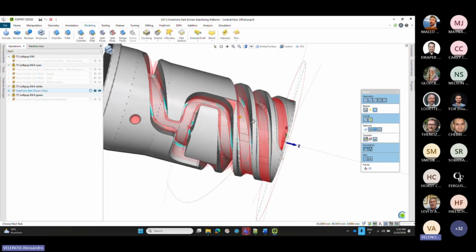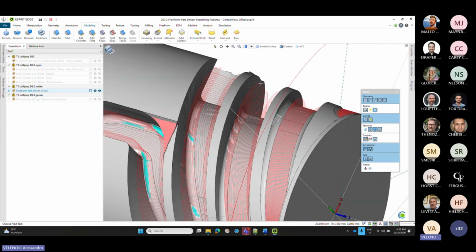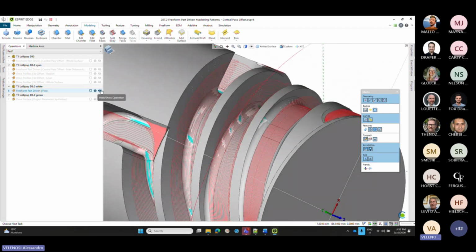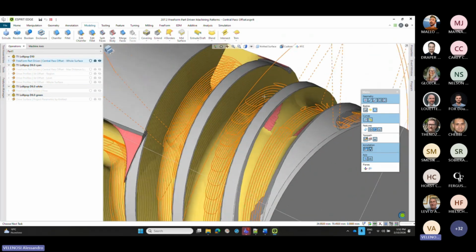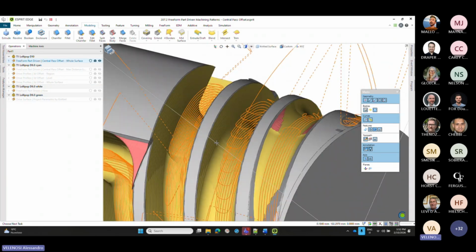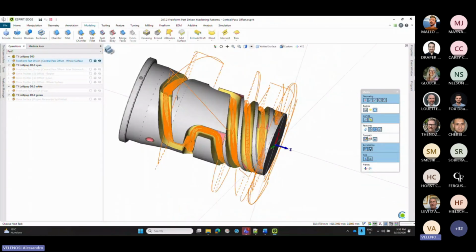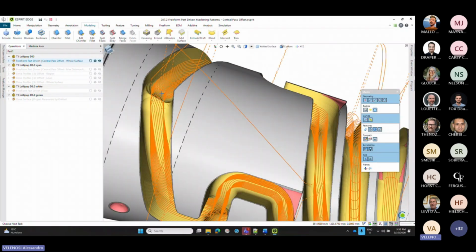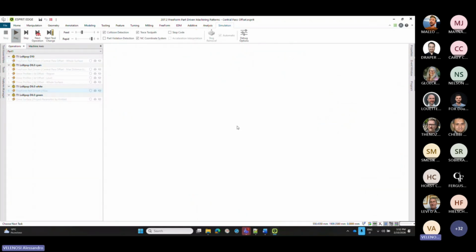As you can see here, avoid the interrupted passes we have on the previous toolpath produced by the central pass offset, where the width of the channel is becoming smaller than what we have on the starting side. So we can simulate it.